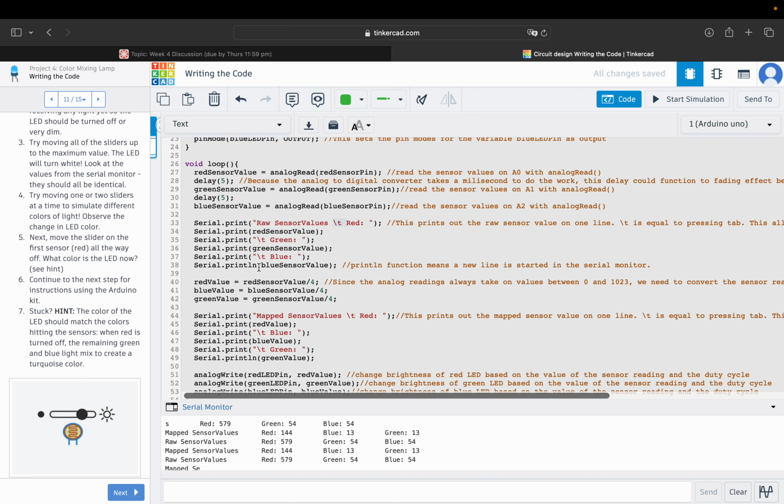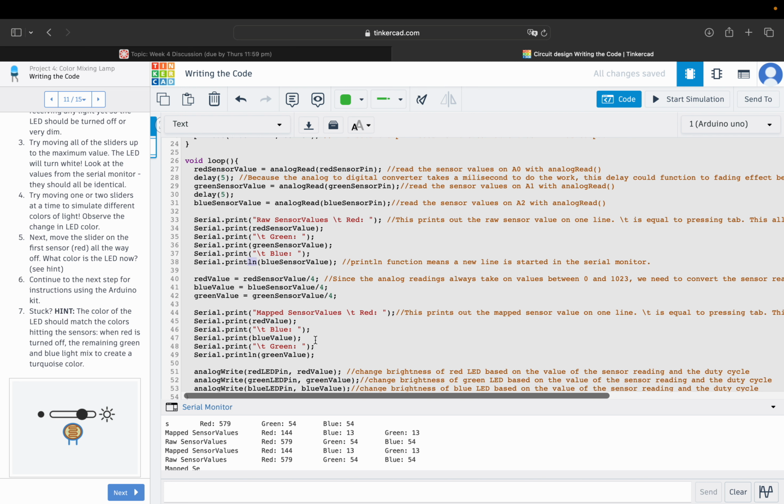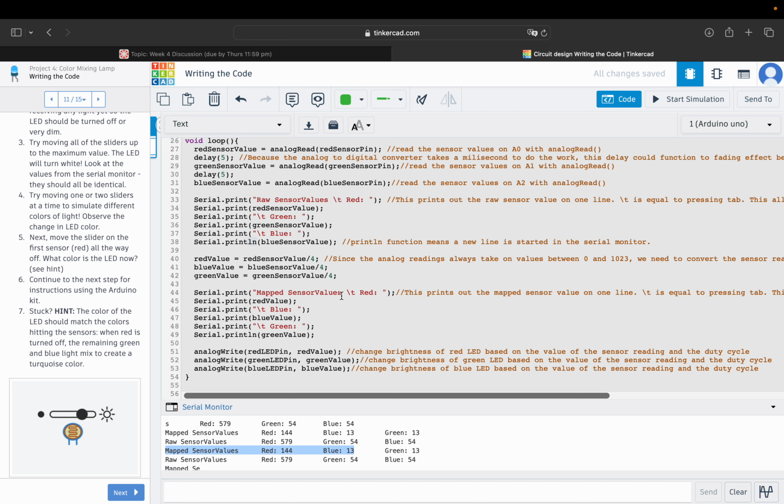And here is the println, which just returns every line. The next line is the raw sensor value, which is the next code here. This is just returning a line so it looks better in the serial monitor. It also explains these codes too. It's just printing the characters and printing the number, which makes it easier to track the numbers down.